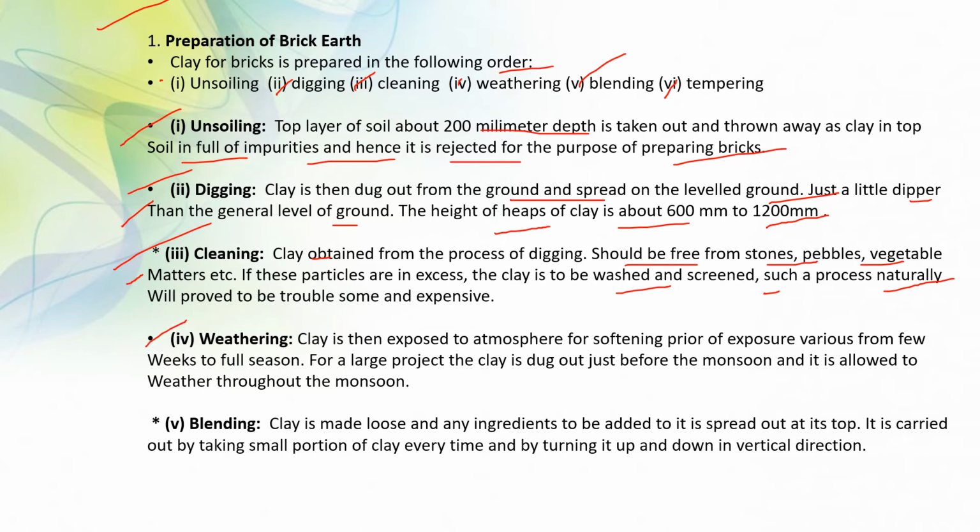Next, weathering. Clay is then exposed to the atmosphere for softening. The period of exposure varies from a few weeks to a full season. For a large project, the clay is dug out just before the monsoon and is allowed to weather throughout the monsoon.